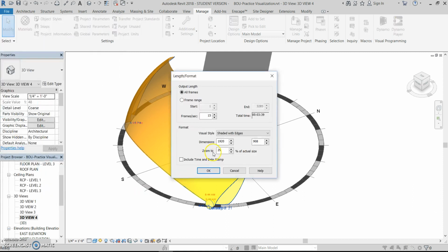a solar study. And with the solar study right here, I do want to include my date and timestamp. And then for the frame rate, let's just bring it down a little bit. This really leans on your hardware, so I'm just going to bring it down to 5 frames per second. Maybe even 3. Oh, I'm going the wrong way. Let's change that to 30 frames per second. So even then, it's going to be a 2-minute video. So hopefully this will work out. So what I'll do now is I'll pause the video and then run this, and I'll see how it goes.